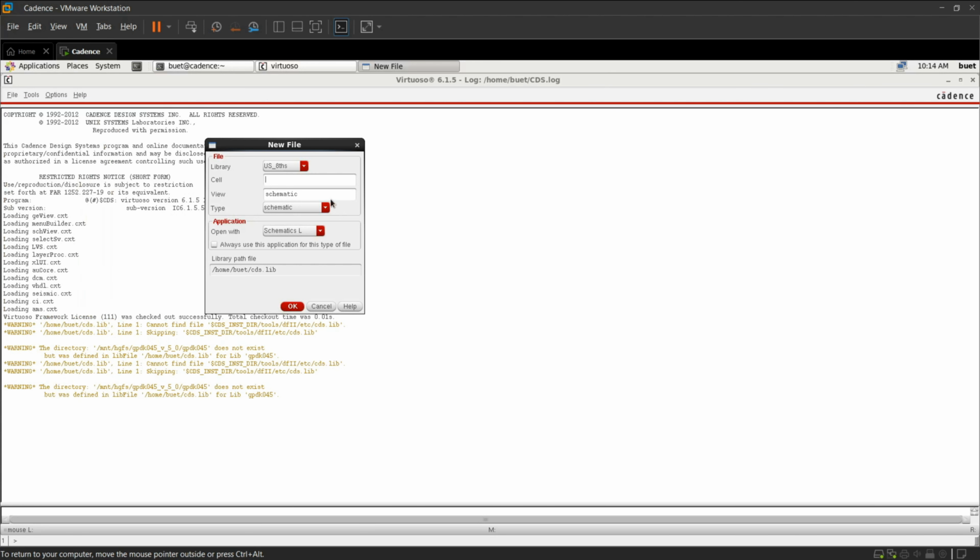As we have done library creation in prior videos, if you have not seen that video, just go through that once, so you will get an idea how to create library and cells. Right now we have already created our library by the name YouTube. A cell, let it be NAND, because we are going to see the NAND gate today. View should be schematic, type should be schematic, open with Schematic L.